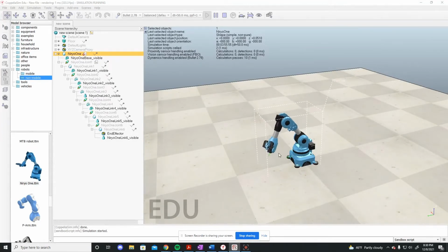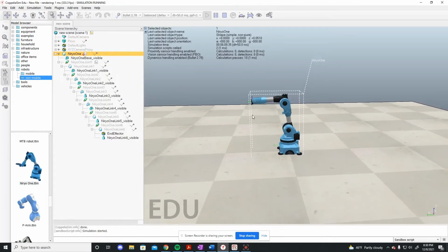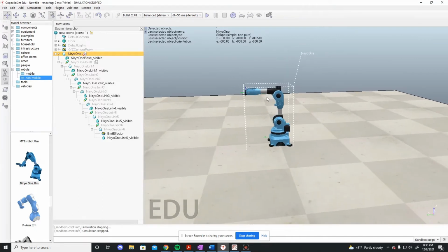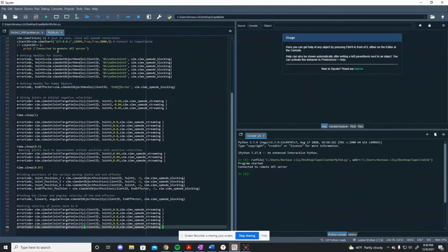So I went ahead and pressed that. So it's going to move down and then move back up. Essentially just simulating it, picking up something and putting it back at the same height. Now as you can see, from looking at it directly on, you can see that this link is no longer going straight up. This link is no longer going straight to the right. And that's why essentially what we're doing is a rough approximation when we do the differential kinematics by hand. Now if I click the stop button, you'll see it actually go back to its initial position. So now it should be straight up again. So the times that I've chosen here, this 1 second in the having the negative values for the velocities and the 0.87 seconds is really just an approximate time to get it back to that initial orientation.